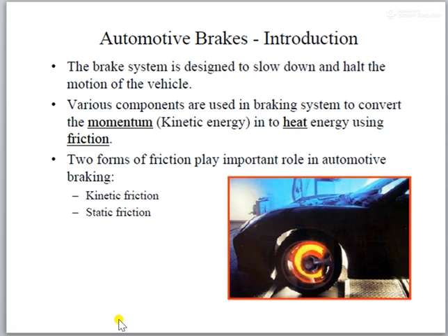So what happens exactly during the braking motion? Whenever you apply the brake pedal, the mechanism present in the road wheels absorbs the kinetic energy of your road wheels or the rotor or the drum, and converts that kinetic energy into heat energy. Not 100% of the kinetic energy is converted to heat energy.